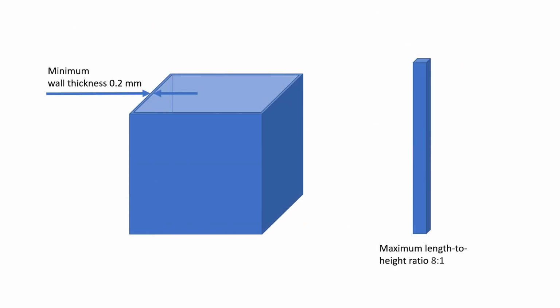The minimum wall thickness of a part depends on the material, the geometry of the part, and the printing parameters. The recommended minimum wall thickness is usually 0.2 mm. However, this is true for relatively small wall areas. If the wall sections are too thin or unsupported, the surface may buckle. The maximum length to height ratio is 8:1. Of course, if the part has a reasonable section or supporting geometry, then it is possible to build a higher slender structure. The minimum strut diameter is usually 0.50 mm.